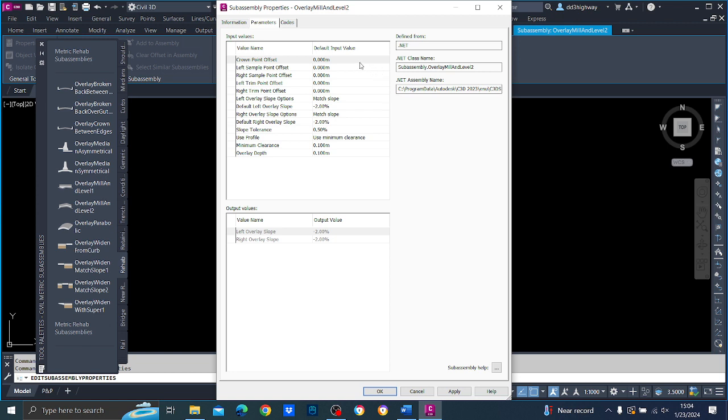So it is 0. Left sample, remember left is always minus. Anywhere if you see the word sample, what they are asking about is the design center, so the design aspects. So this is the design lane width they are asking. So it should be minus 3.5. Understand? Remember, anywhere you see left, it should be minus. If it is sample, they are asking about design details. Right sample, right should always be plus.